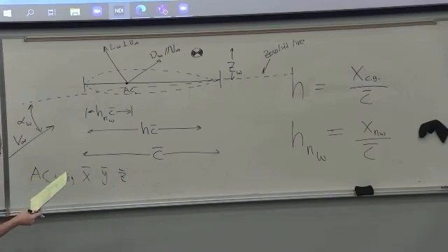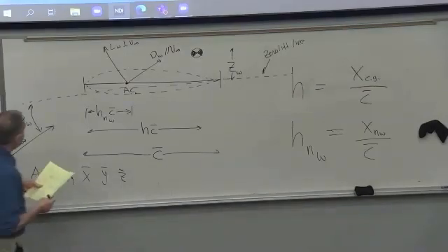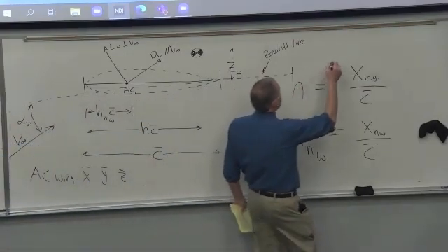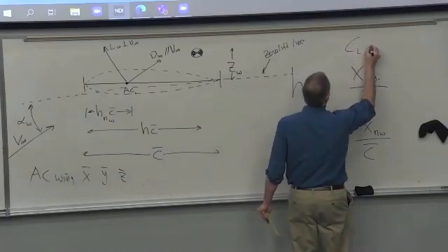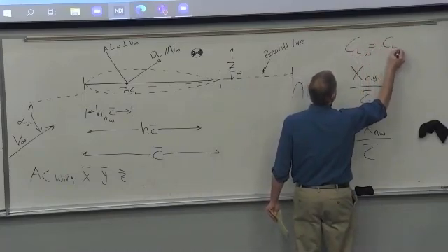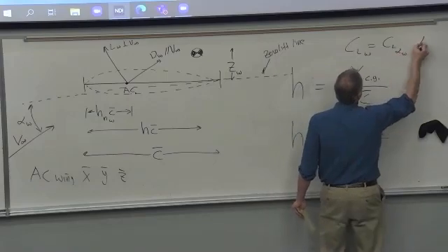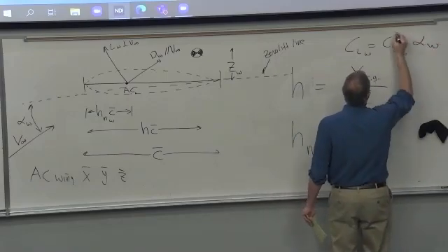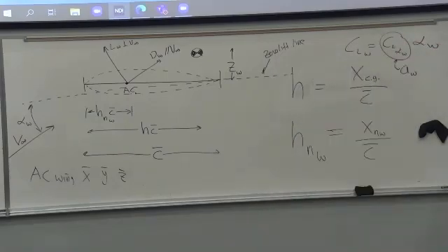That was step 5. Let's see, step 6. We're good. We already did that. That's defining the lift. Guess I need to write that over here. CL of the wing is the lift curve slope of the wing times alpha of the wing. And sometimes this is called A for the lift curve slope.